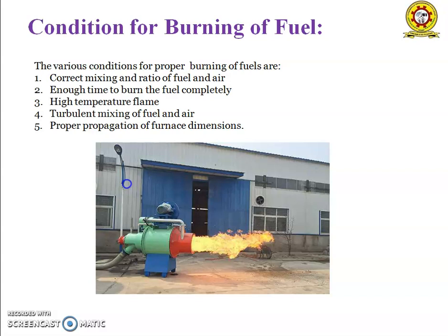The flame shape is controlled by the secondary air valves, and the control adjustments are incorporated into the burner. Secondary air, if supplied in too much quantity, may cool the mixture and prevent it from heating to the ignition temperature. The coal-air mixture should move away from the burner at a rate equal to the flame front travel in order to avoid backflash into the burners.